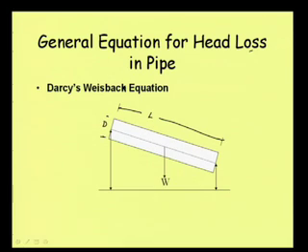On the upstream side there will definitely be a pressure force from this side, and from the downstream side there will also be a pressure force. Rather than equating them, we need to see how much pressure force acts from each side, and also the shear force exerted because of the shear stress tau 0 at the boundary.